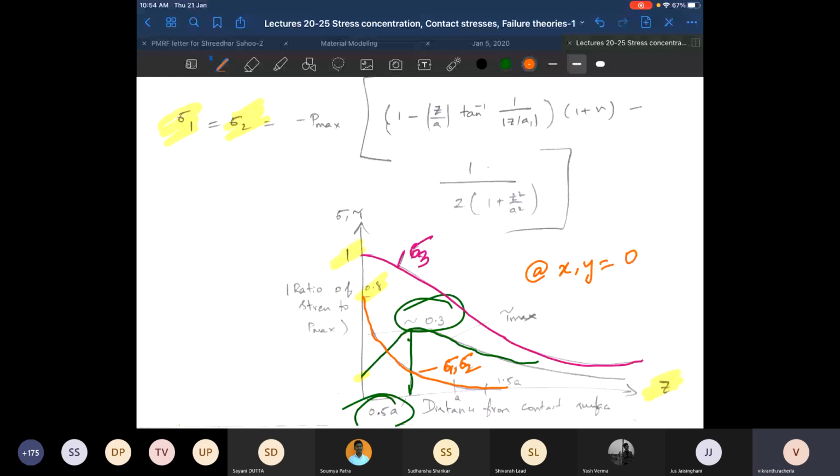If you take this rail wheel contact, except for locomotive wheels, none of the other wheels actually have any motors or traction being generated, so it's near pure rolling condition. If you take pin joints, in the majority of joints you would want them to be frictionless. Where you do have friction, it is still only a small fraction of the normal load.